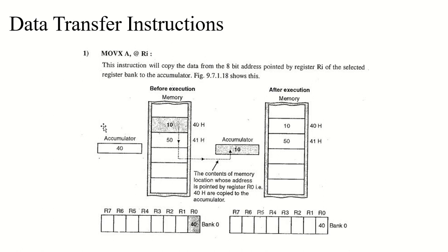So this instruction will again hold only a single byte, will take 2 clock cycles in total, and again tell me what would be the addressing mode. It would be the register indirect addressing mode, because we have the @ sign here. Again, no flags are affected here.